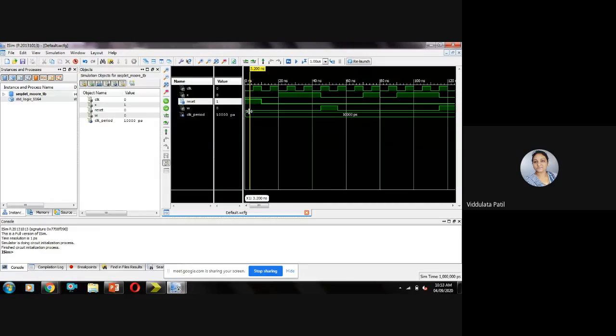That means the output signal has a particular fixed value. It is not an unknown value, but a certain fixed value, and that is very important whenever you are designing any application, that all your signals must have a certain fixed value. You must have observed that in most ICs you will get this reset signal, so that we get the output signal at a particular fixed value.